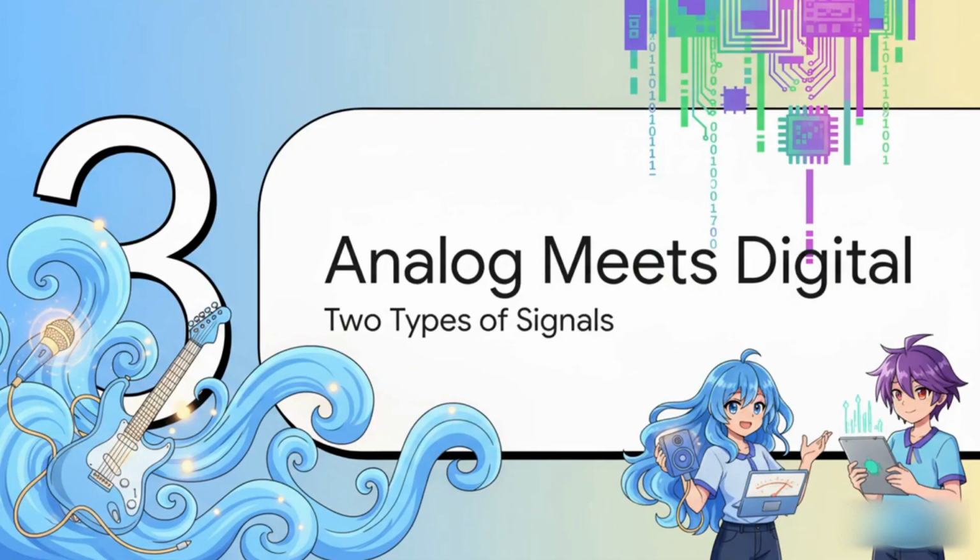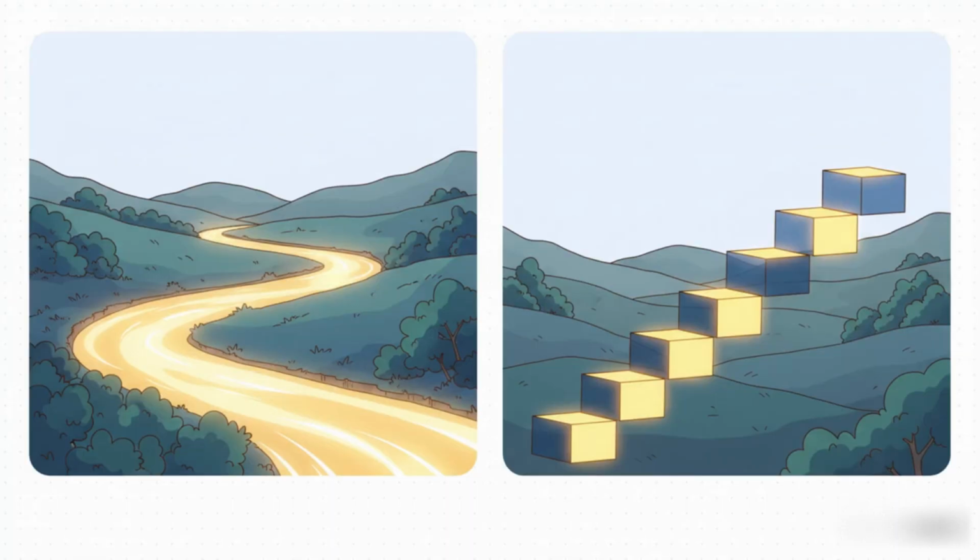Before we peek under the hood of an amplifier, there's something really important we need to cover. Signals basically come in two main flavors, analog and digital. Analog signals, think of a smooth ramp. They're continuous, they can be any value within a range. Digital signals, on the other hand, are like a staircase. They can only be at specific levels or steps, usually just a high or a low, which we call a 1 or a 0. What's really cool is that a ton of modern gadgets actually use both. It's called mixed signal design, and it lets them get the best of both worlds.